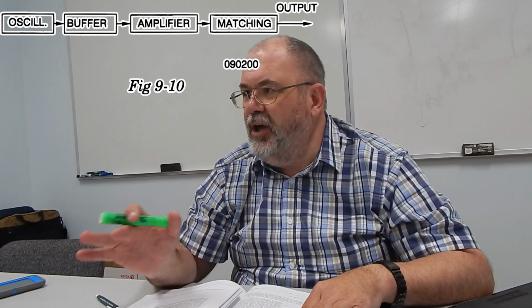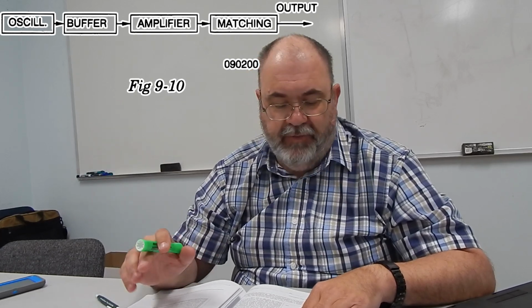The buffer amplifier is actually optional. There's many, many simple QRP transmitter designs that are just oscillator, amplifier, done, no buffer. But it's a good idea to put a buffer in there. It lets our oscillator run nice and clean and free and with no encumbrances. Then we amplify that because we want to put out a little bit of power, more than a couple of milliwatts that would come out of a little small signal transistor. So we can amplify that up to, well, if we use our grounded grid configuration and a 3CX25,000, well, 25 kilowatts, no problem.